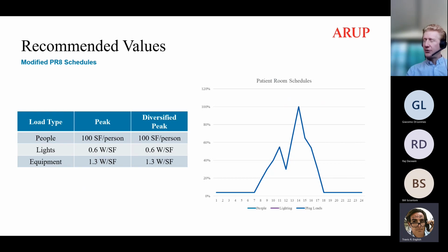Yeah, like these. So it's a good question. I probably should have paused and clarified more. Since our framing was looking at the annual energy simulation and not looking for these values I have on screen at sizing. And the two can be inherently tied together in the same model, but we would schedule that with a separate sizing run. And a separate sizing schedule. These are looking at the annual energy use schedules.